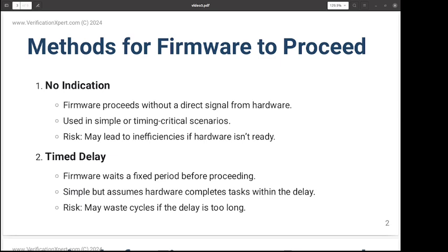In our previous video, we designed an AXI-Lite based adder where we simply write register A and register B, and simply read some register. There we assume it is already done after writing both registers. But if it is more complex than an adder, it will take some time to do the processing.